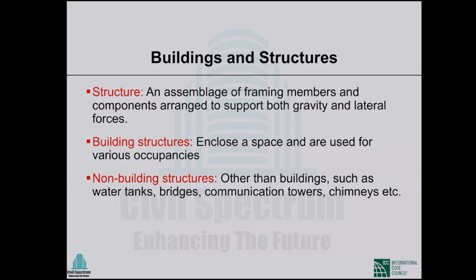Yes and no. For example, even for the design of non-building structures, we use the building code to determine load. For example, the seismic load. You use the zonation map even to design bridges or other non-building structures. And there are some tables related to wind load, related to non-building structures. So from that perspective, this is partly covered, but the details of design of non-building structures are not covered in the building code.